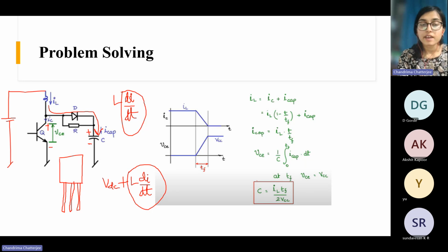And then when you turn on again, this MOSFET will be on, and the capacitor will get discharged via this R and through this MOSFET or BJT, like this. Then it can discharge through this R and through this path. So this is called the RCD snubber or the shunt snubber.